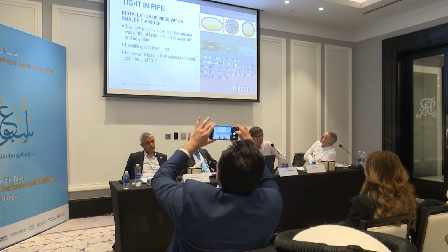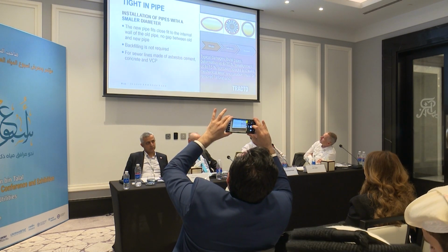We have got the ability to recalibrate the shape of the pipe that's in the ground. So if you have slight damages or ovality, we can send the calibration head through to make it perfectly round again before we put the new pipe into the ground. So there's very many ways. We've also got the ability to do standard swage lining with a pipe burster.